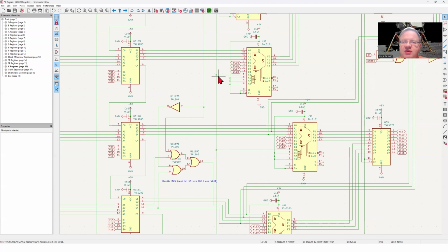In this case, we only need to worry about the OR function, so we can just ground S1, S2, S3, setting them to 0. Then we've got S0, which we set either high or low, depending on whether we want a pass-through or the logical OR.